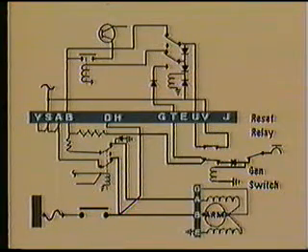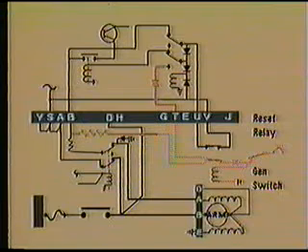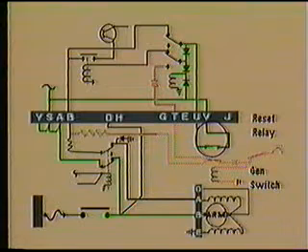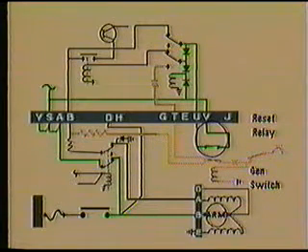When the generator switch is moved to the reset position, the reset relay energizes. The closed contacts of this relay will now provide bus power to the control panel and to a 400 ohm resistor connected to the A lead of the generator. Another set of contacts of this relay will complete a path for current to flow from the B lead of the generator to a pair of diodes within the control panel and to the A lead of the generator.